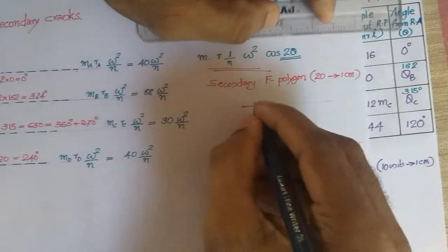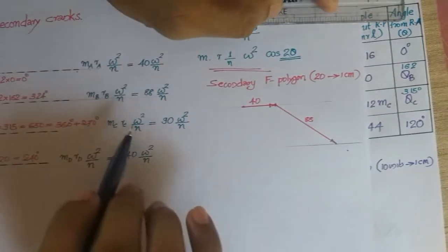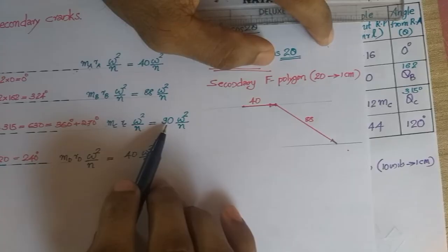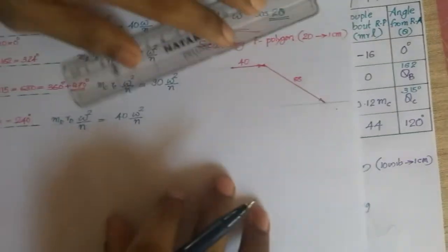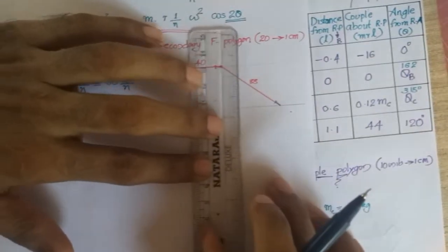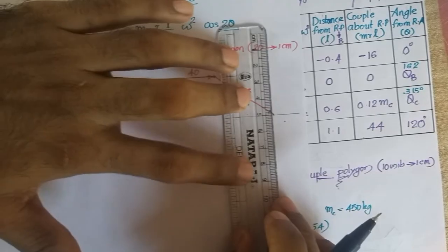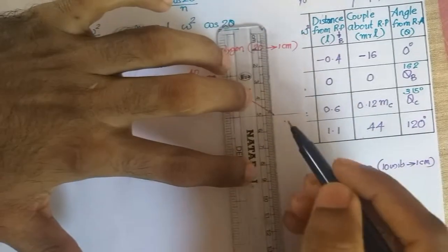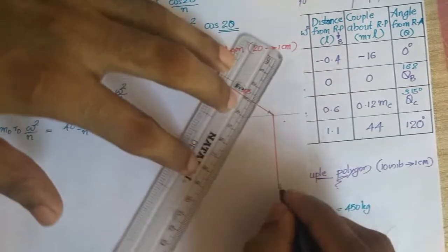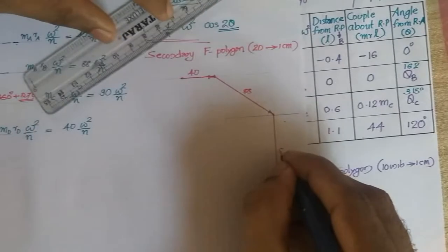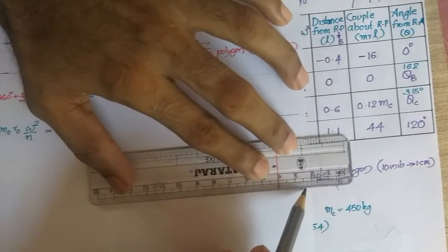Next you have to mark the 90 unit vector, and that angle is 270 degree. So it will be coming vertically down, and the length of the vector is 90 units or half, that means 4.5 centimeters. This is the end of the vector representing 90, and at that end also we will be drawing the horizontal line.